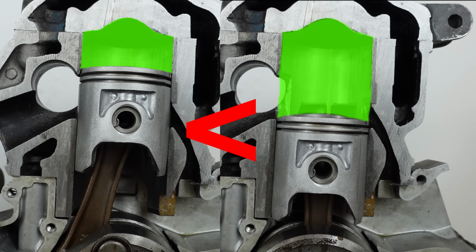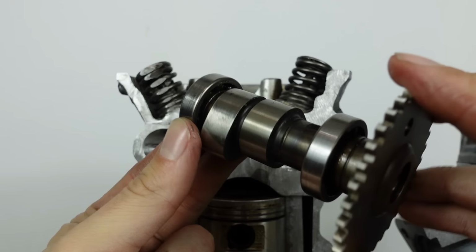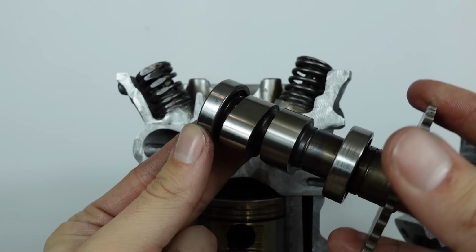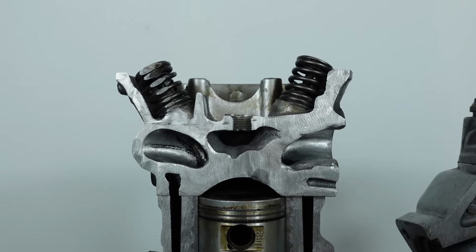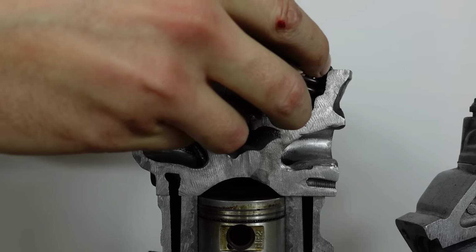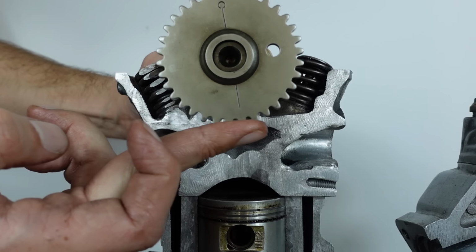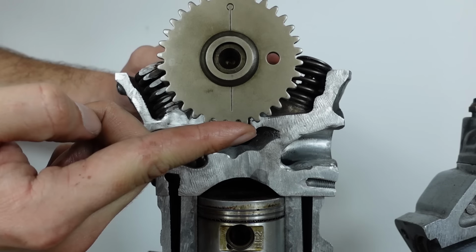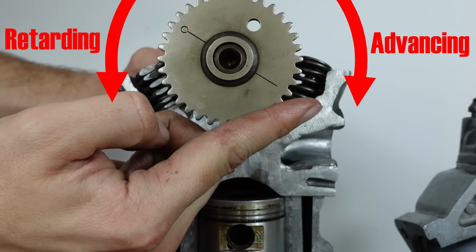The final difference is that the 4-stroke is inherently more flexible thanks to its more complex, bulkier design. And the key factor behind this lies in the camshaft. A camshaft is essentially the mechanical brain of the engine, and changing the camshaft can completely transform the character and performance of the engine. But you don't even need to change the camshaft. You can simply shift its angle in relation to the piston, which is known as advancing or retarding the camshaft to impact engine power and torque.